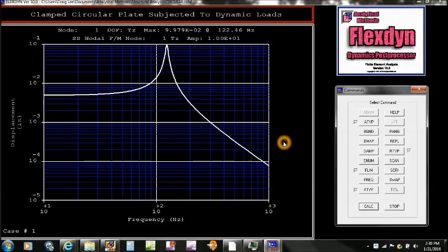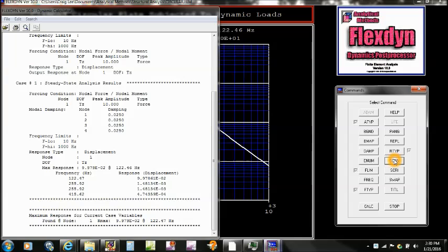So now if we wanted to determine where is the largest displacement on the plate under that loading condition, we could come over here and just hit scan, and it will look around and say, okay, so I am right at the maximum displacement, which isn't a surprise. It's right underneath where the load is being applied in the center of the plate. So a large steel plate, a tenth of an inch thick, 10-pound oscillating force in the middle, you get about a tenth of an inch displacement.